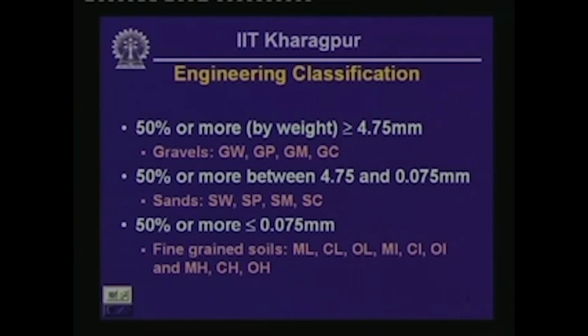Now, we move on to the engineering classification of soils. Here, for coarse grained soils, we want to classify the soils according to their grain sizes, because the engineering behavior of coarse grained soils, as you have learned earlier, is mainly governed by the interparticle interlock.